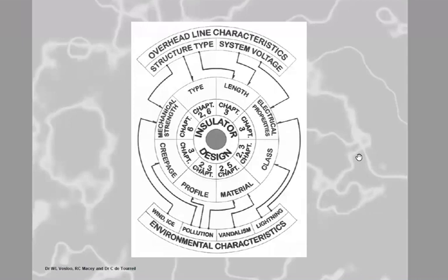So you need to be able to select this insulator, but select it optimally so that you can actually say, I want this thing only to flash over 1 in every 20 years, or no, I want it 1 in 50 years. To be quite honest, I had a problem to solve in Eskom, which I'm going to show you, where they actually wanted it to flash over only 1 in a million years. Now, let's be honest, okay? I don't think a nuclear power station is going to be around in a million years. It's not going to be around in 100 years, okay? But you find sometimes bean counters can actually come up with the most amazing, let's put it, design philosophies.